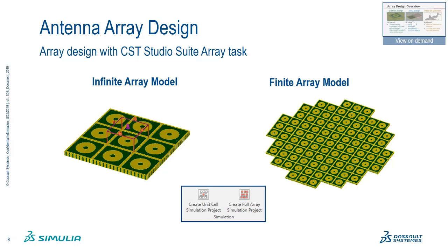Following that, full array simulation is used to check the performance with a finite number of elements, for example, to check for edge effects. And both the infinite and the finite array models can be easily generated using the array tool in CST. Also want to mention that there is a video specifically about array design available from SIMULIA at the link on the top right-hand corner of the slide. But let's take a quick look at how the array tool works.